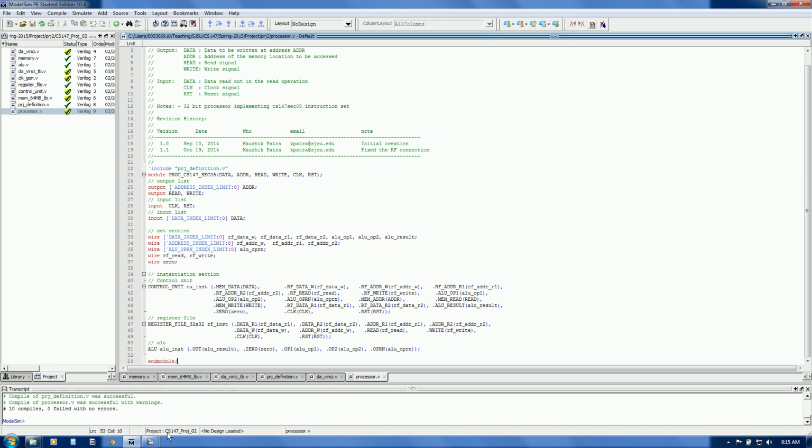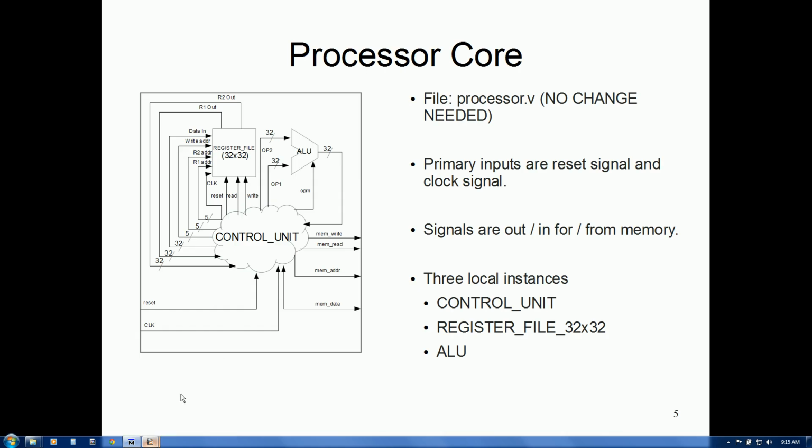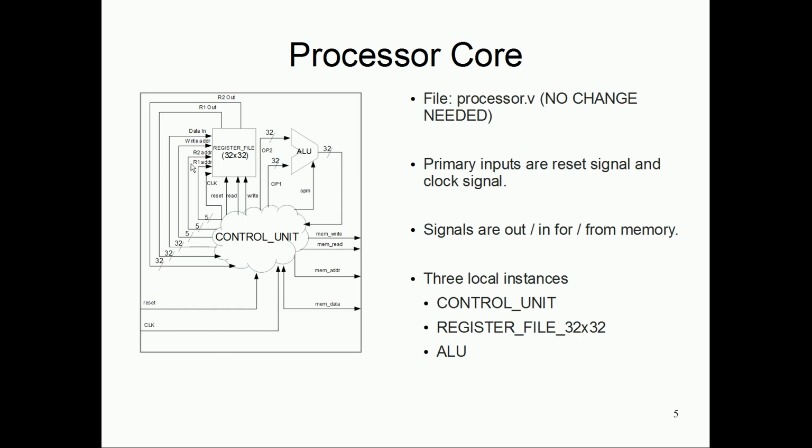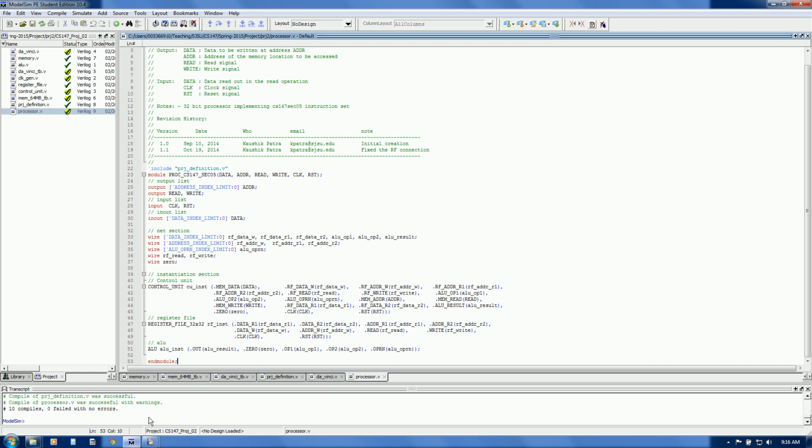Those are all internal signals. These are all wires for us. Only these are input ports, these are output ports, and inout data is this. Everything else is an internal wire to us. So we are defining each of them in that specific file, and then we are just stitching them through the ports and the wires. We are stitching all of them, and that is the whole system.